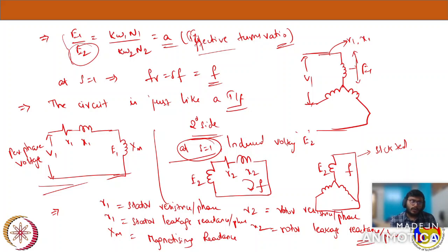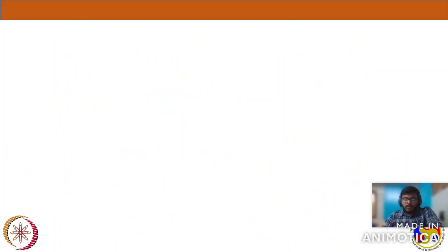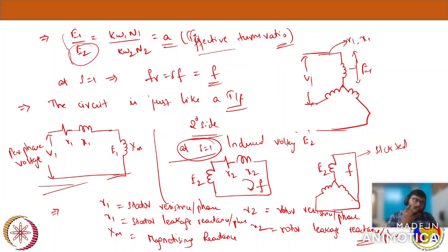Only then can you get the actual impedance that the reactance is offering, because the values keep changing with frequency. When the motor runs, say our motor is rotating, the rotor frequency will change because the condition of slip comes into the picture. The rotor frequency fr will keep changing as the slip changes, so the reactance value must be modified every time.